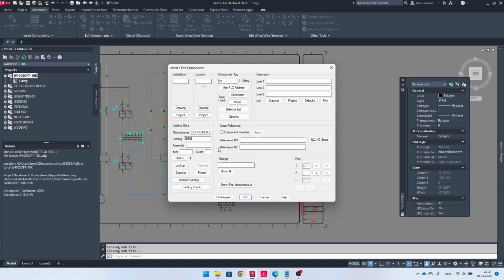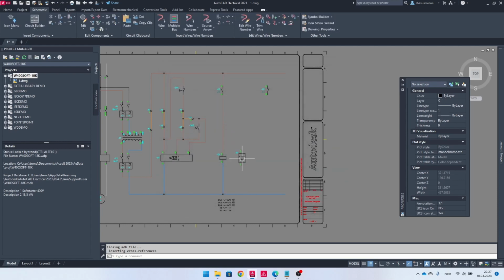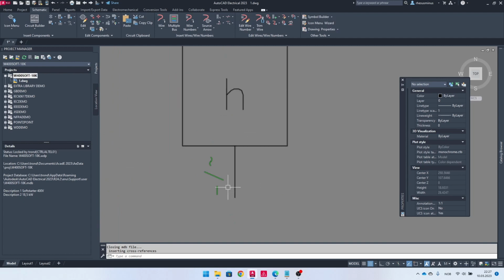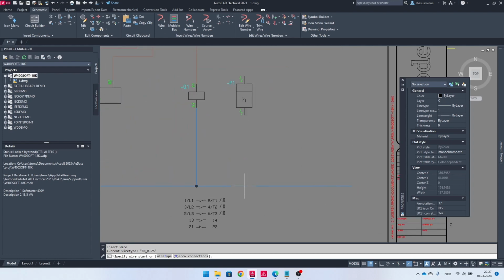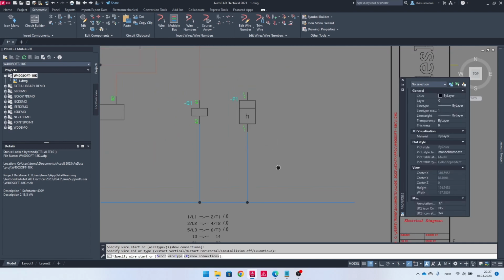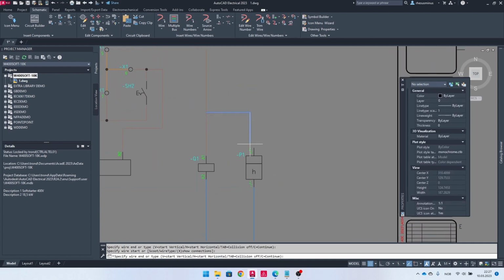No, it didn't really like the tilde character there. Well, I'll just do -/. I'll just do it manually. I have no idea why it didn't work, but well, it is what it is. I'll do OK. I will map the symbol to the character. I should get the pin numbers correctly like this at least. And I will just add a wire here as well. From here up to here. And I need one from here to here.